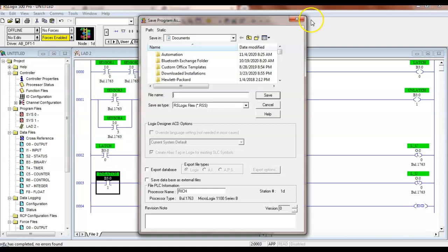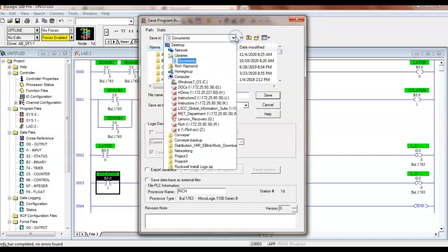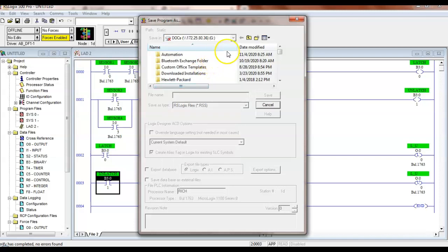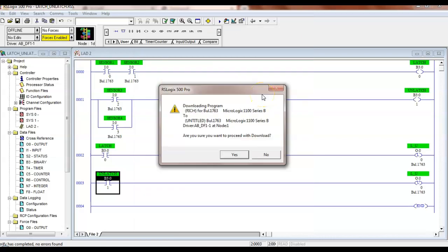This is where we would change where we wanted to put it. Okay, so it says it's not available. We call it remote mode, so we can switch it between its other two modes with our computer, right? And what are the three modes the PLC can be in? Program, run, and remote, right? What are the two modes our application can be in? Offline and online.